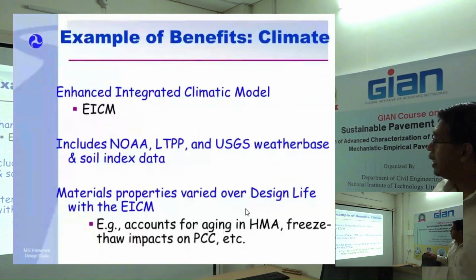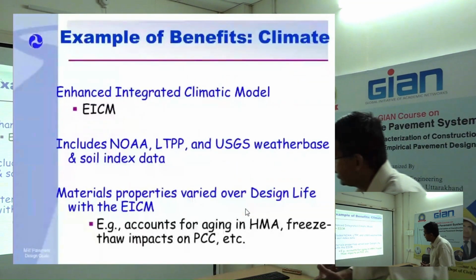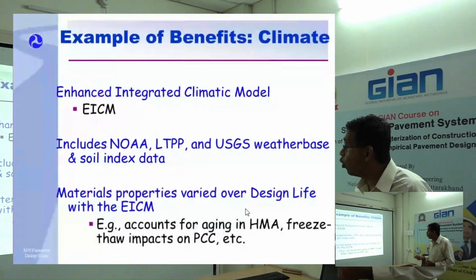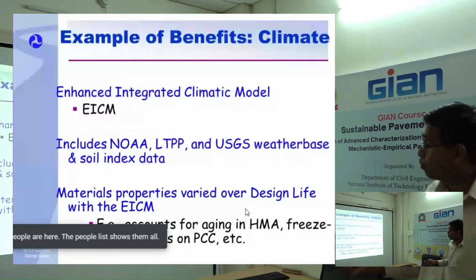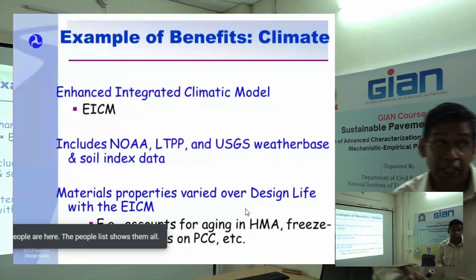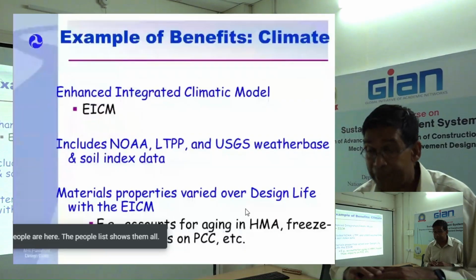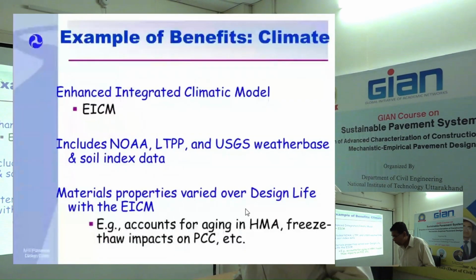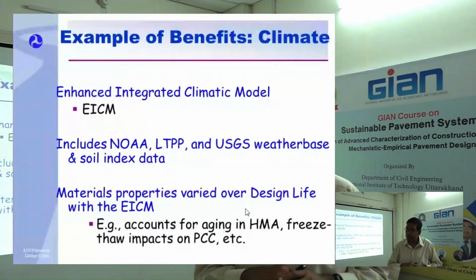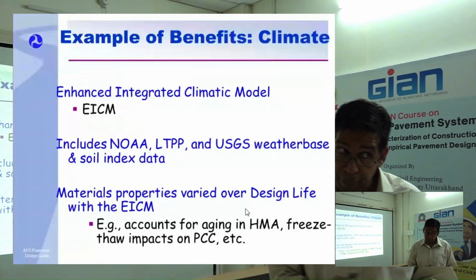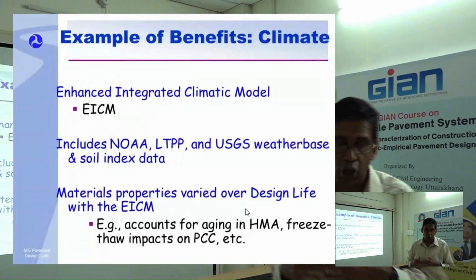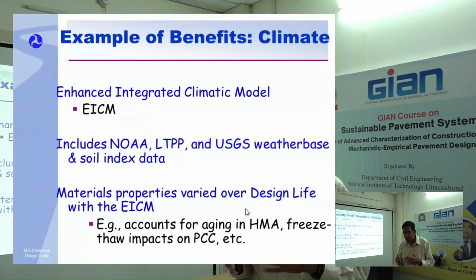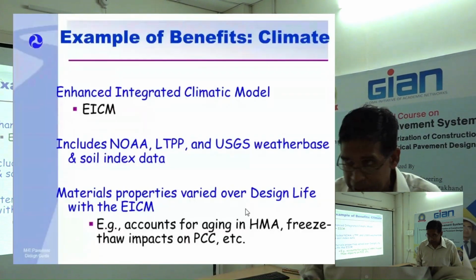It includes NOAA, LTPP, USGS weather and soil index data. Material properties vary over design life. There is aging of hot mix asphalt, freeze-thaw impact on PCC. It is not only for asphalt, it is also for concrete. In fact, for PCC, this AASHTOWare ME is completely solid. For Portland cement concrete, they have gone way ahead, and it is doing very well. In asphalt, it is not doing as well because it's a lot more complicated material.